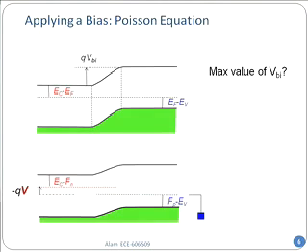Similarly, on the left-hand side, the negative side, although I have pushed up the Fermi level, the red dotted line, the gap between the red line and the black conduction band must remain the same, because N, the number of electrons, must be equal to ND, the donors, even in the presence of bias. As a result, the gap between them will remain the same, except that the whole conduction band on the N side will be pushed up a little bit.